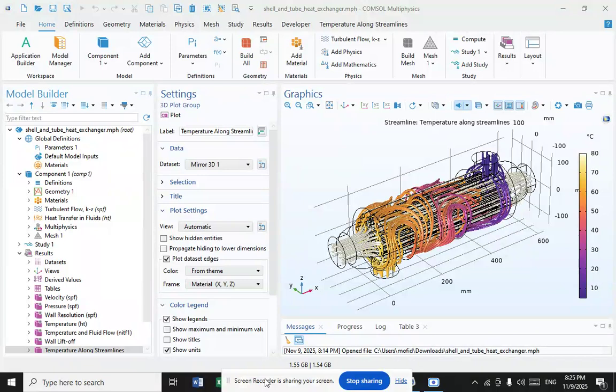There are several variations of shell and tube exchangers available. The differences lie in the arrangement of flow configurations and details of construction. In applications to cool air with shell and tube technology, such as intercoolers and charge air coolers for combustion engines, fans can be added on the tubes to increase heat transfer area on the air side and create a tubes and fans configuration.